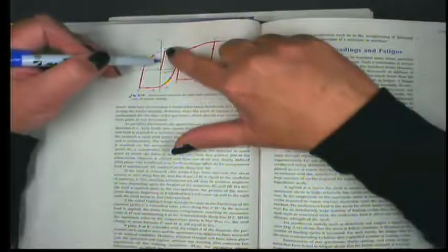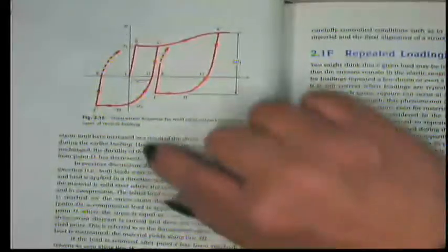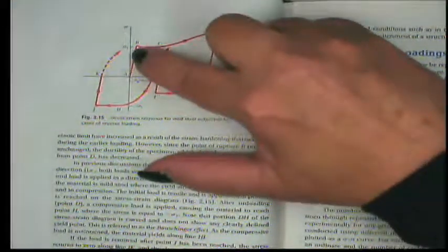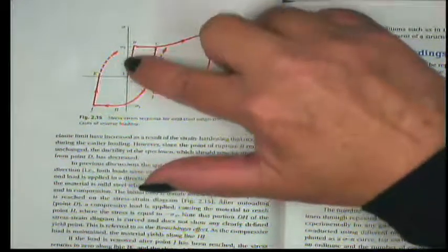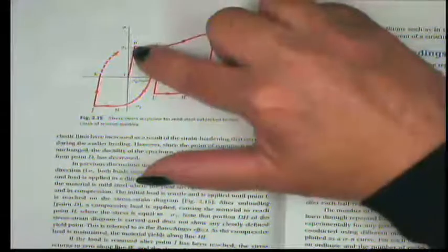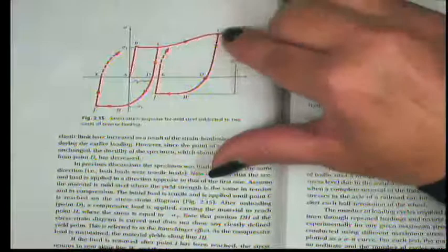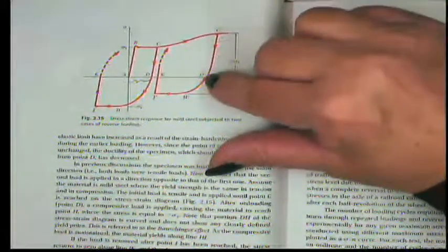And if you notice, here's our run home to what we know. The line A to B shows us that elastic behavior. Whatever this material is, this is a mild steel. What happens is we pull on it until we exceed the yield, and we have this highly ductile type of behavior. What happens then here from C prime to D prime is we are unloading it.